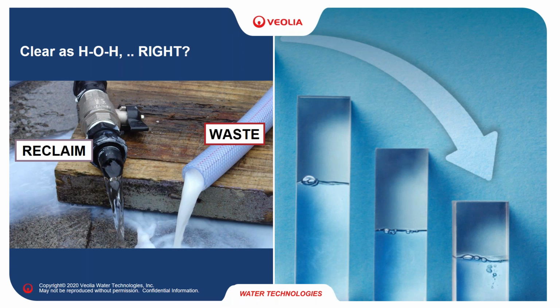Sure. If you recall, the refinery or the site was having problems not just with quantity of water, but quality of water. And anybody that's ever operated a cold lime softener will understand how that might happen. It's a very difficult piece of equipment to maintain consistency with. So with the ongoing demand in the refinery for a given quality of water, by expanding the capacity through a mobile clarifier, it enabled the cold lime softener to begin to work within spec and produce a better quality effluent.